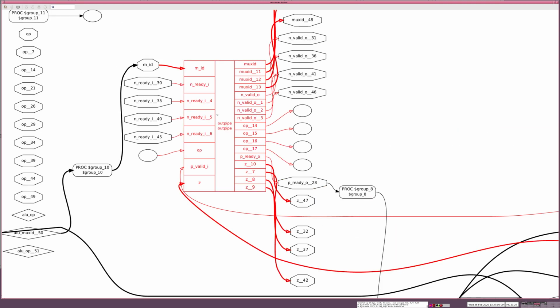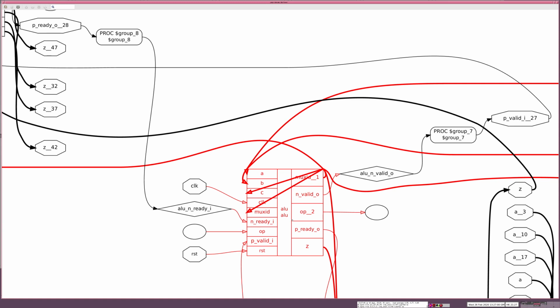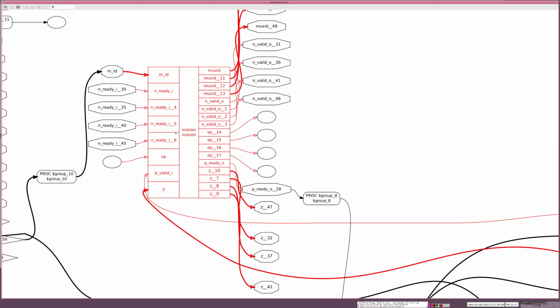Now this is multi-in and multi-out. Okay, so this is why it's multi-in, single out, because this is a multi-stage pipeline block, and to keep it fed, in a 6600 design, you have to have concurrent function units, which Mitch also very kindly explained. And the way that works is any data that you need for the ALU. So if you have a 4-stage pipeline, you need a minimum of 4 of what they call function units at the front of it to capture the data and feed them on contiguous cycles.